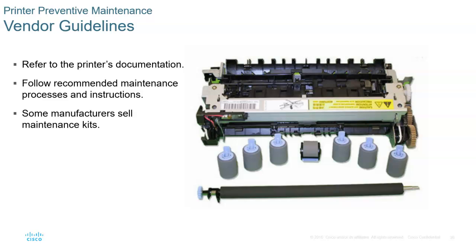Do be sure that you watch the inkjet printer preventative maintenance video. It talks about making sure that you replace ink cartridges, that you clean the print heads, that you remove paper jams, and that you get rid of the dust, dirt, and debris that you might have there.